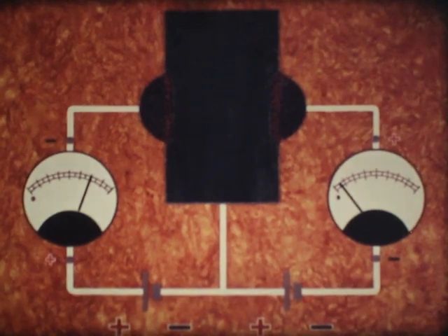This is due to the comparatively large width of this N region. However, if we considerably decrease the width of this central region, more and more of the holes emitted by the left-hand P region will be absorbed by the right-hand P region, and the currents flowing in the two circuits will become very nearly equal.